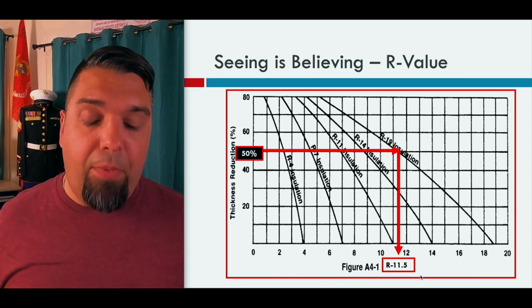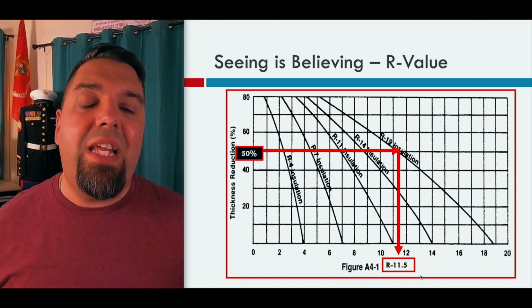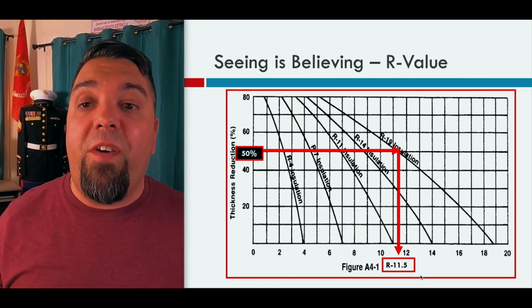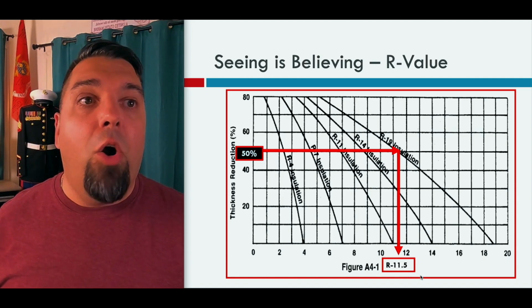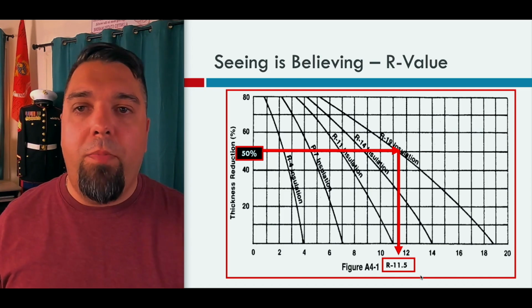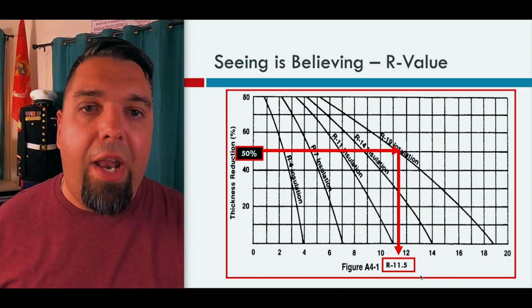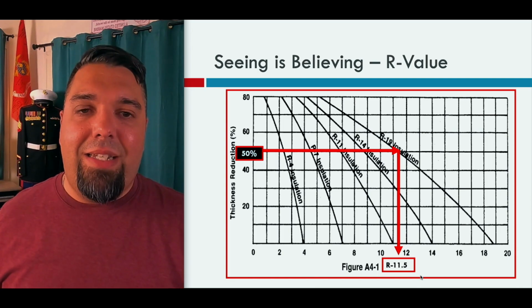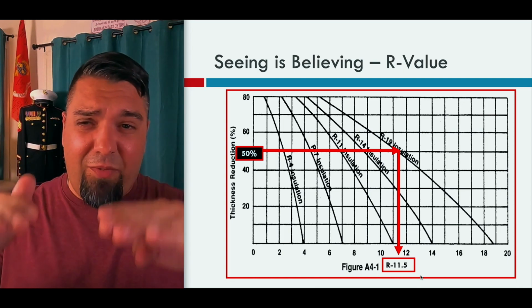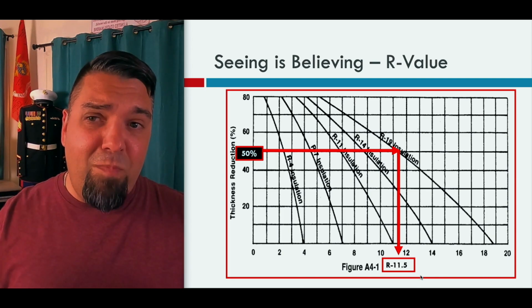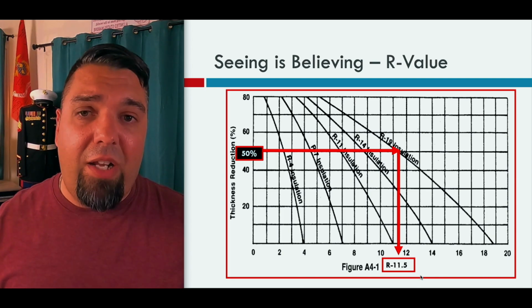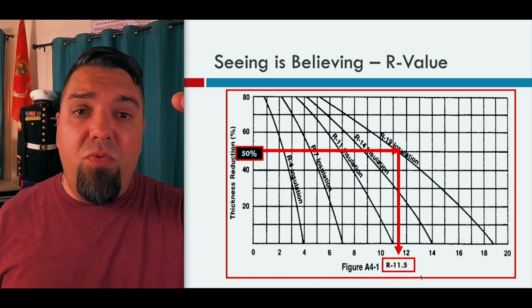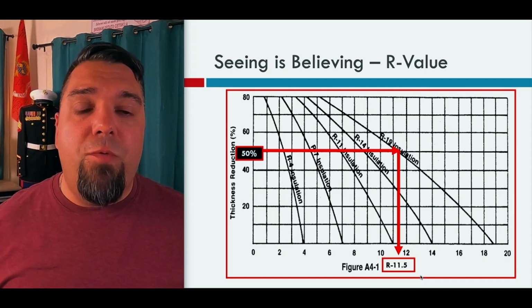So as an example here, if I had 2% voids, or let's say that insulation was not professionally installed and a homeowner did, they just went down to Home Depot and rented the sprayer and just threw it in their attic. And it looks just all wavy through there. In that instance, I have to kind of get an average of the height, and then I would say there's probably some voids because I didn't install it correctly. So I would actually derate my R value for the insulation.